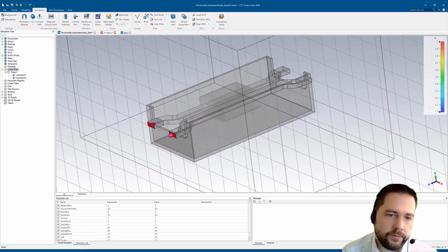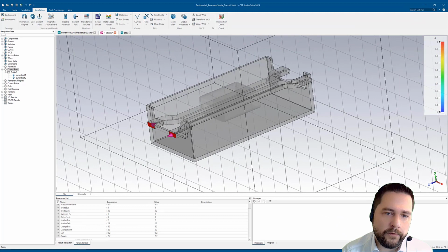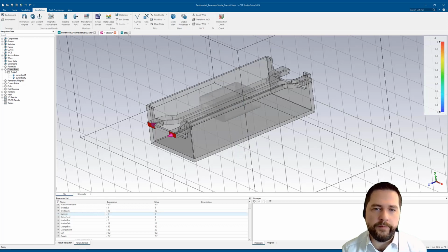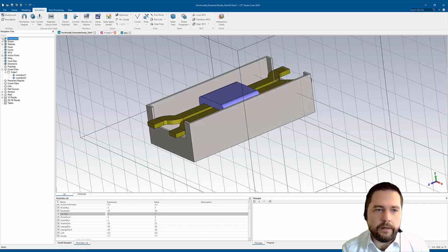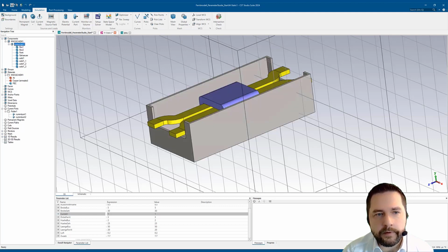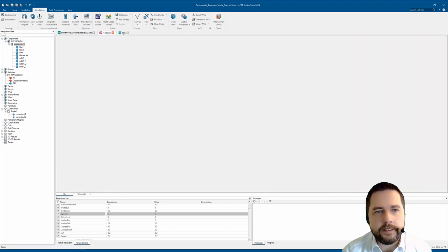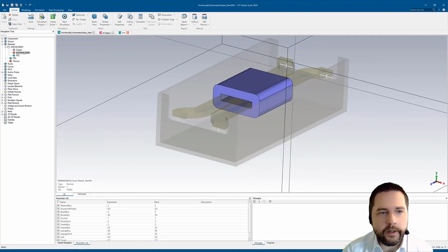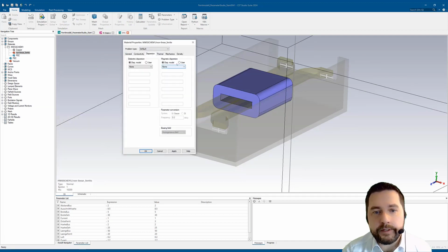There you can see it. We have a differential mode current defined on both bus bars. One is going in, the other one is going out. And we have a current parameter defined so that we can do a parametric study of the influence of the current on the permeability. Of course, we also have to apply the normal material for copper to the bus bars for the low frequency simulation, and then we can switch over to the high frequency simulation, where we will define the ferrite material